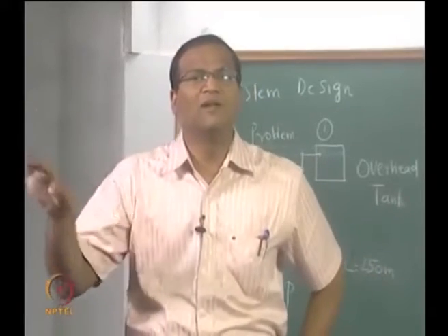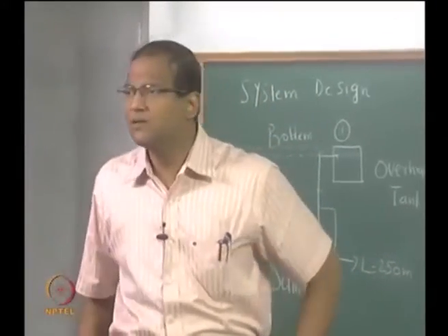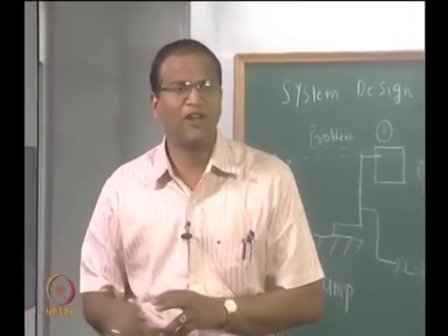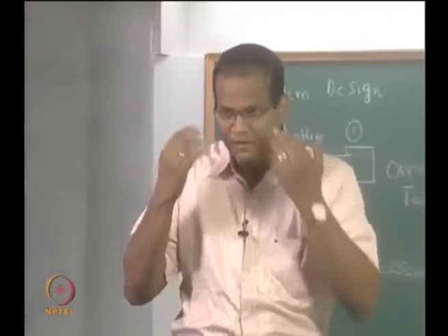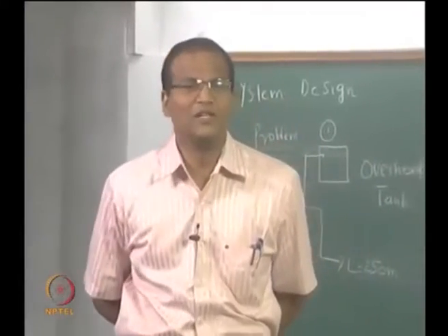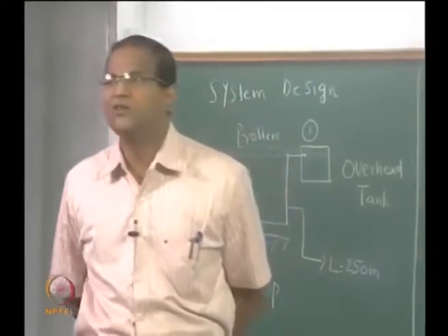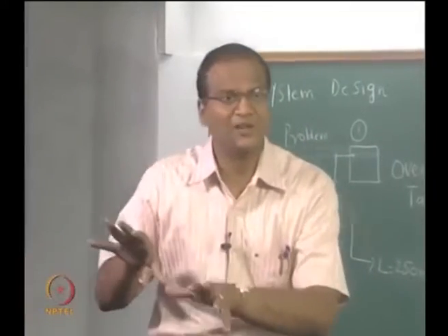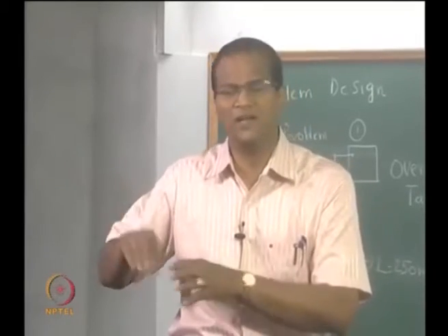So there is a limit, there is a cap on the maximum delta T which is allowed. What is that value? 5 degrees. It is about 5 degrees. Otherwise the green activists will cry. Okay. Even otherwise it severely disturbs aquatic life if the delta T is more than 5 degrees. So a constraint is already coming up in your design. Okay, you are allowed only 5 degrees.